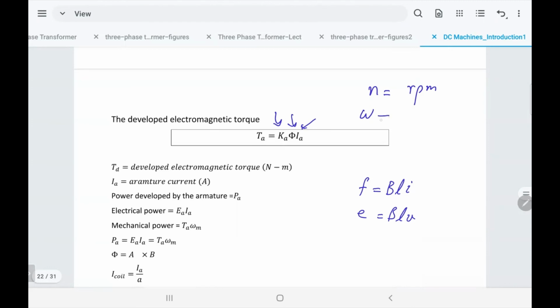So how can we find omega? Usually when they write on the machine, they don't write omega. They write 2,000 RPM, so you should convert it to omega. And by the way, mechanical is equal to electrical, let me remind you. Omega in electrical, what is it? 2 pi f, right? But f was cycles per second, hertz.